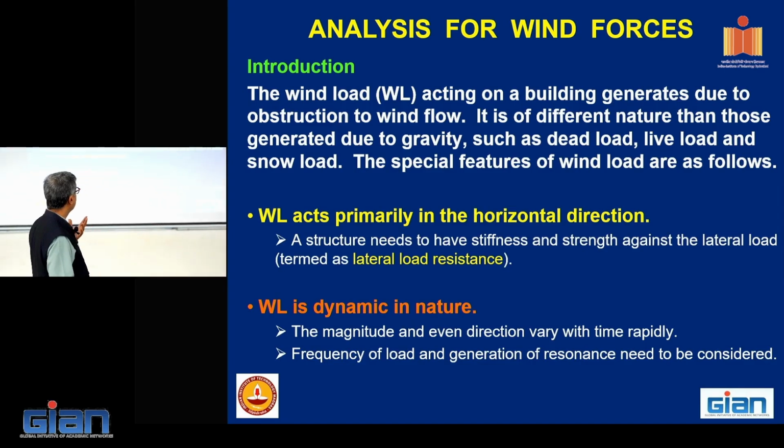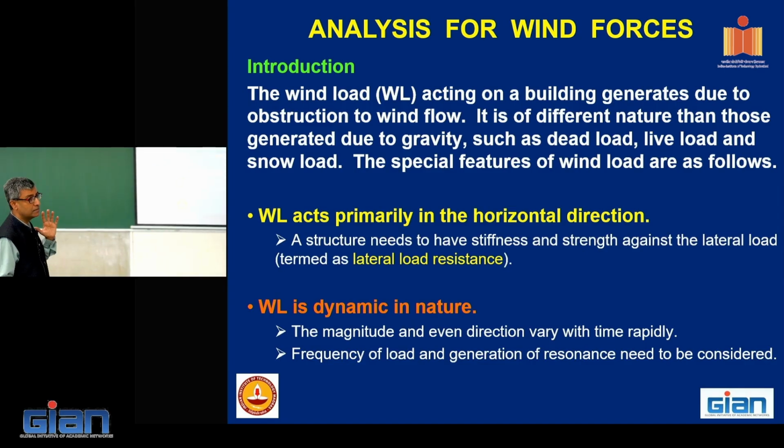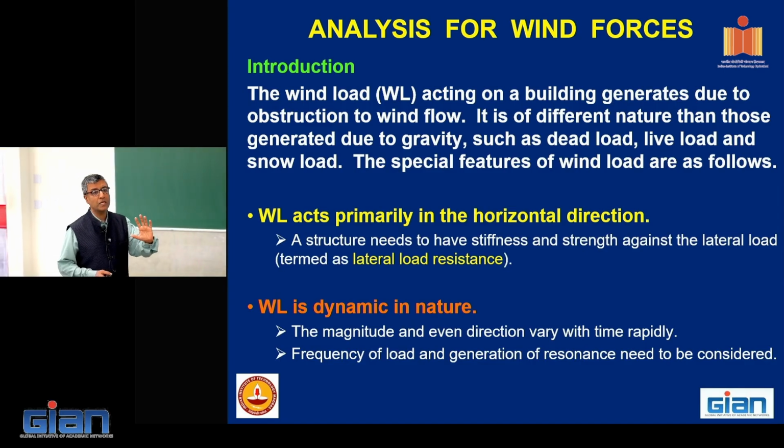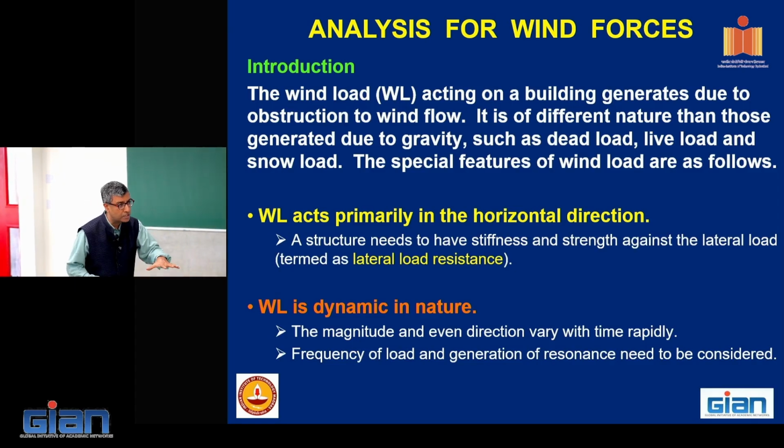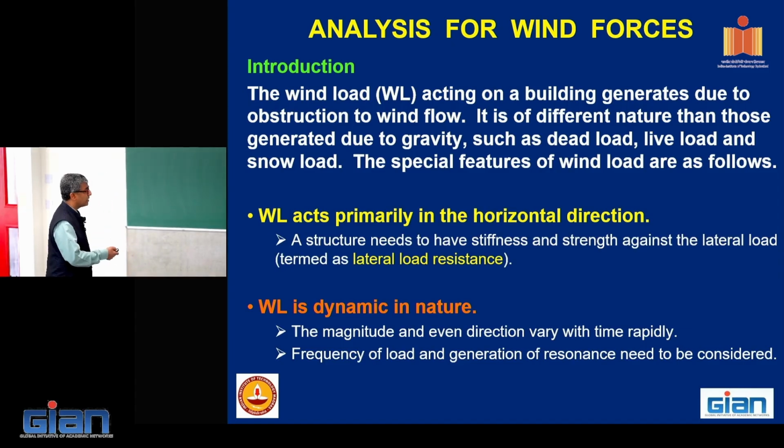Wind load is primarily in the horizontal direction. That means now we are talking of a different direction of loading. Till yesterday we were talking of only gravity loads, but today we will be covering loads which are in the horizontal direction. And hence a structure needs to have proper lateral load resistance. It is dynamic in nature.